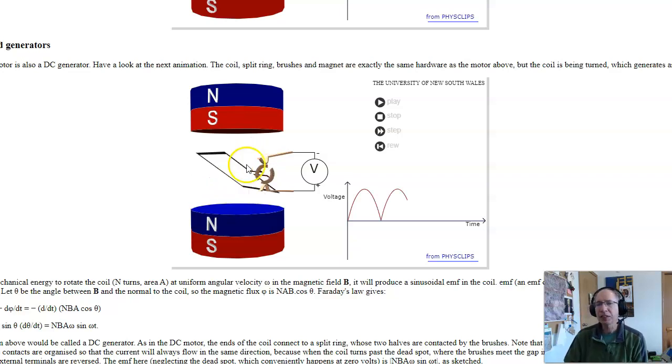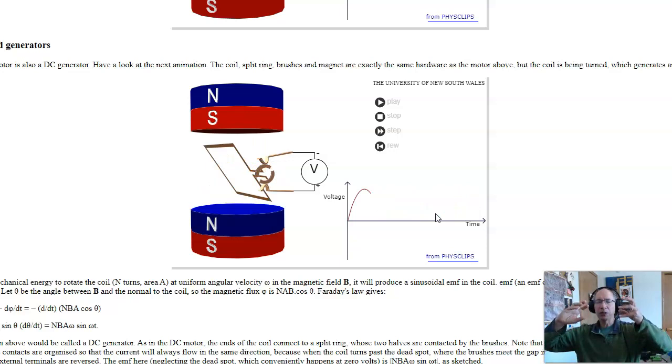Now this isn't actually how DC motors are built. The problem with this design is I have a very erratic torque, and so you're going to shake your teeth out. What they typically do in DC motors is they'll add 6 commutators spinning around. So I just pull off the peak for one phase in the rotor, then another one switches in, then another one switches in, and it just gives you the peaks, making a much more constant DC generator. And from duality, apply a DC signal, I'll get a much more constant torque. Plus they take the rotor and twist it.